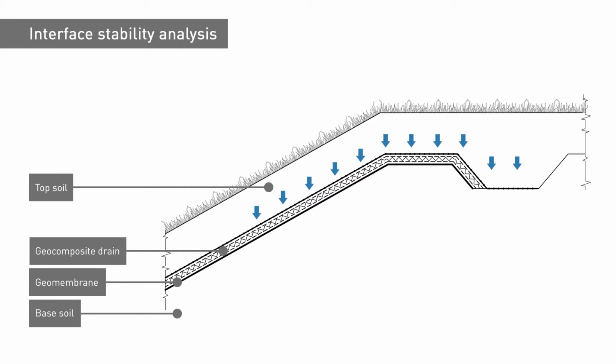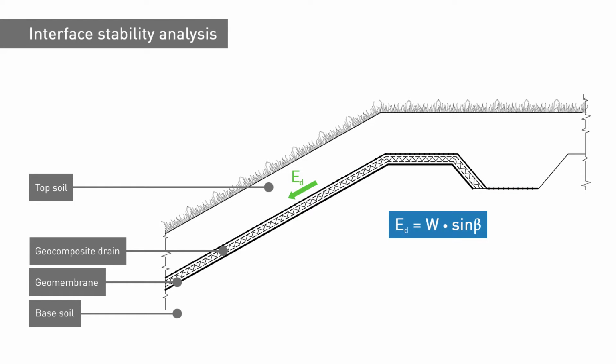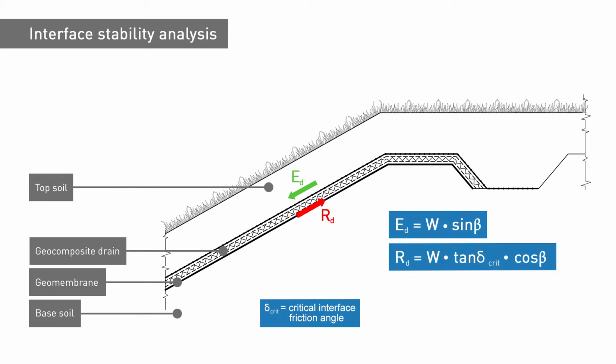The destabilizing force generated under static conditions is opposed, assuming an indefinite slope, only by the resisting force exerted by the critical interface which has the lowest value of the angle of friction. We assume, therefore, that the resisting force is purely frictional, and consequently the critical interface represents the possible failure surface.